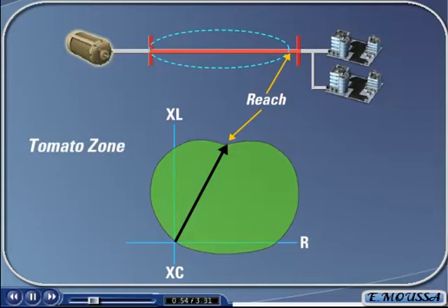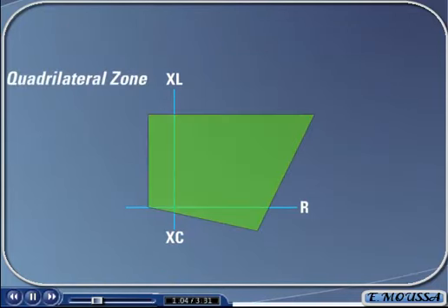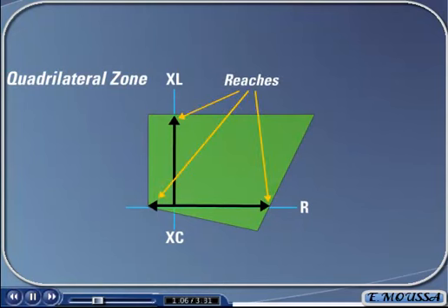A tomato-shaped Mho characteristic allows for faults that have more of a resistive element to fall into its zone of protection. Another custom zone is known as a quadrilateral zone of protection. This type of zone allows you to set the reactance and resistive upper and lower boundaries to create your own custom shape to match the needs of your power system.